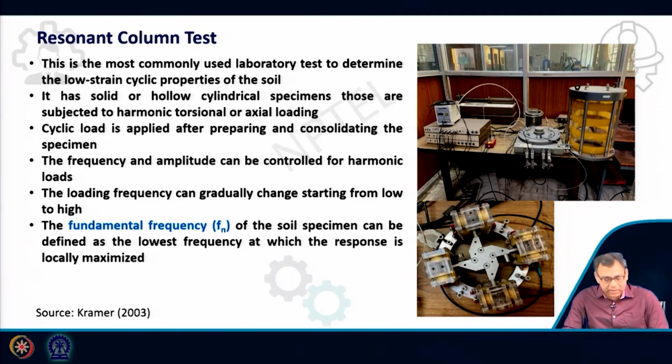The fundamental frequency of the soil is determined, which can be defined as the lowest frequency at which the response is locally maximized. So, first we will get the fundamental frequency. What is the fundamental frequency? It is the lowest frequency at which we get the locally maximized response. That is called the fundamental frequency, which we identify.